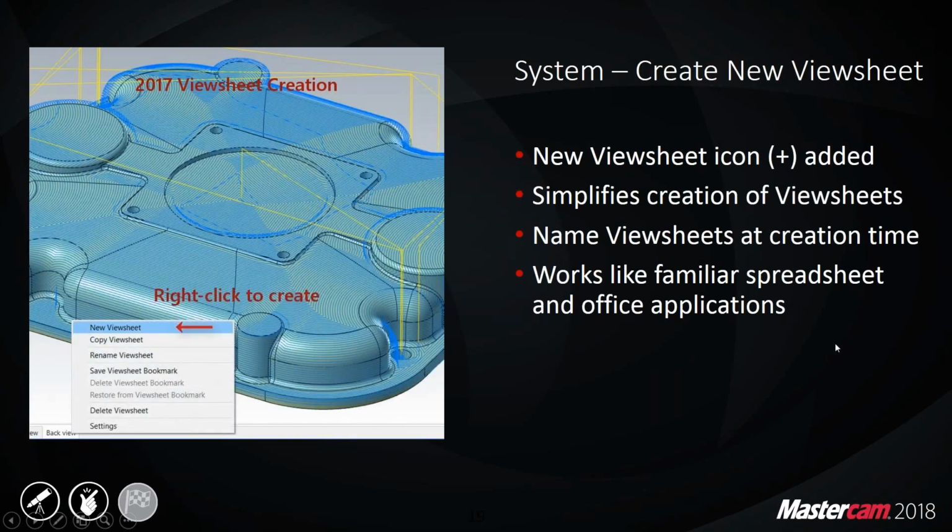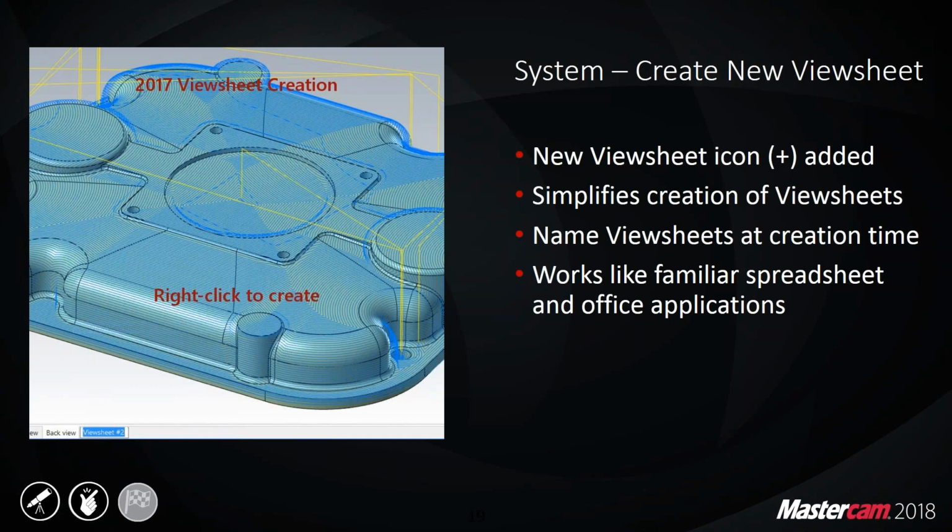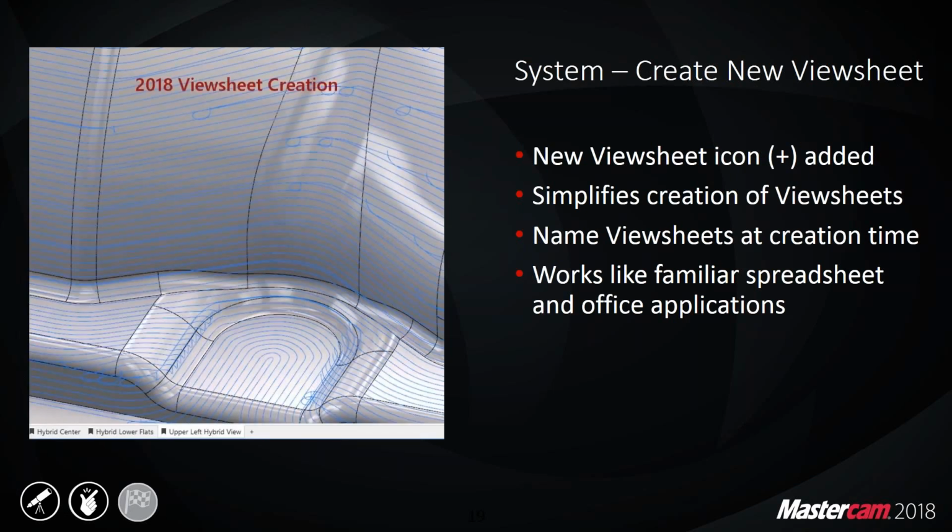So I can't do a raise of hands like I did in the in-person rollouts, but every time I ask if people are using view sheets, I get maybe one person in the room that is using them. And I can't stress enough how useful they can be, because you can basically set any command you want in Mastercam as far as the setup is concerned to a view sheet. So your planes, colors, levels, entity attributes, what view you're oriented in, and so forth.